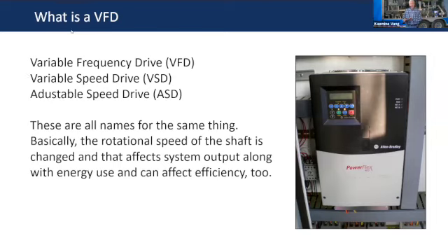All right, so what is a VFD? Variable frequency drive. Well, variable frequency drive is one name. Variable speed drive, same thing. Adjustable speed drive. You hardly ever see this term anymore, but they're still used a little bit. Usually we call them VFDs because it's just become the go-to, but any of these are the same thing. And it basically changes the rotational speed, how fast that shaft is turning from the electric motor, say, going to the bowls and impellers.